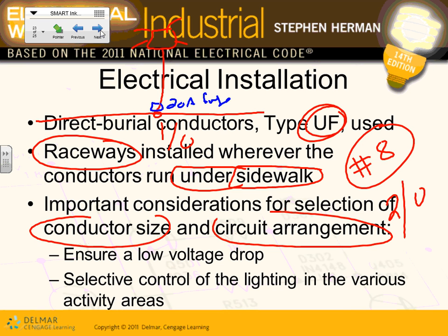So this conductor is number 12, and this conductor here is number 1/0. And they keep going from fixture to fixture to fixture. Does that make sense? So you have an inline fuse, they call it inline fuse. By doing it this way, they get a low voltage drop, and they also still maintain protecting the number 12 conductor inside the pole. You don't want to put 4/0 all the way to the fixture. Any comments, any questions?